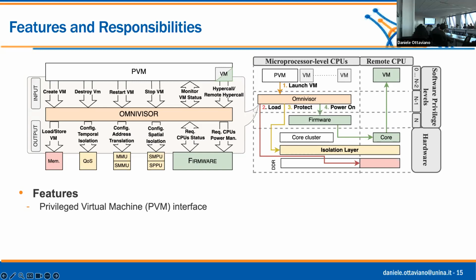The partitioning thing doesn't apply on the FPGA, right? So you still have the translation going on. Yeah. If you use the FPGA, you can actually use the SMMU or IOMMU to do the address translation. But you have to, right? You can disable it, but yes, you can use it.